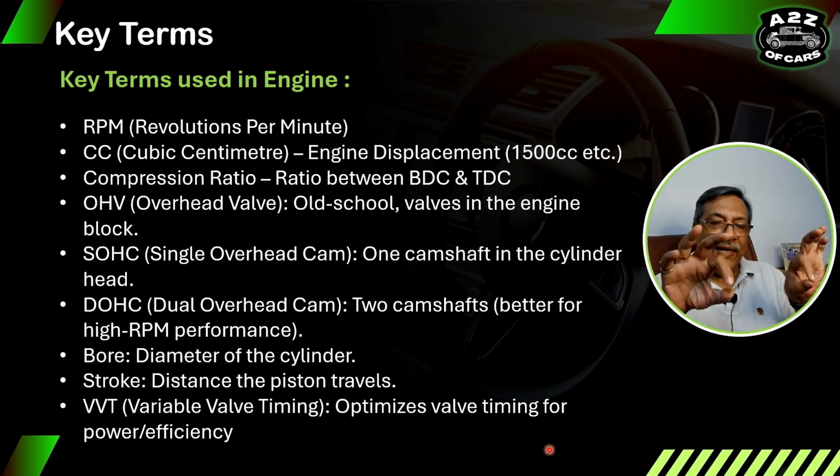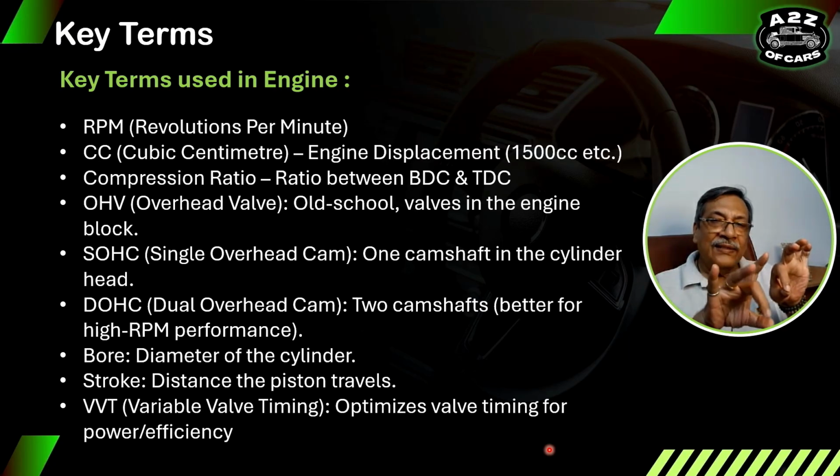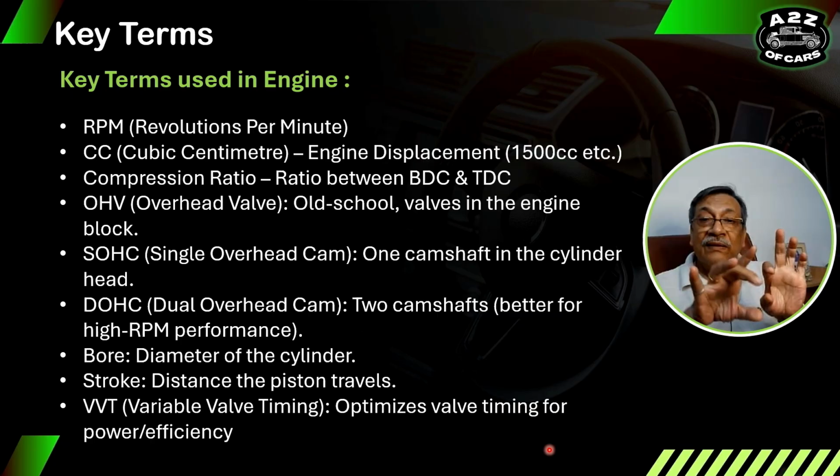So here we have the normal size cams, and then there is a bigger oversized cam in between these normal size cams. After a certain speed, there's a lock in between. So now this lock happens, and the valves open and close because of that oversized cam.